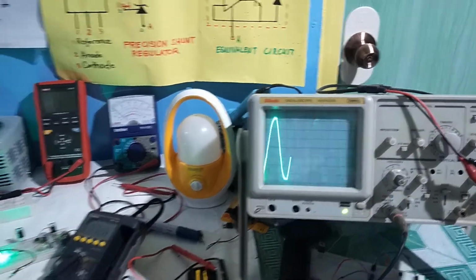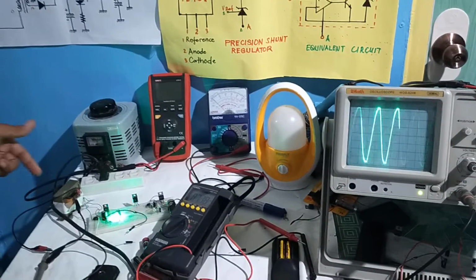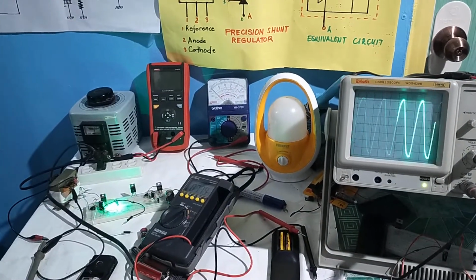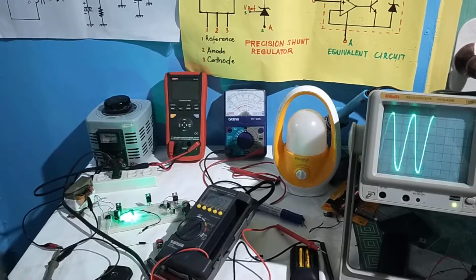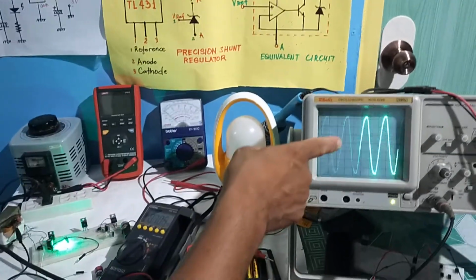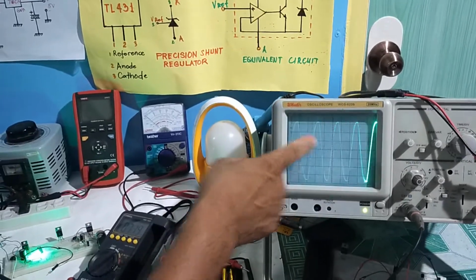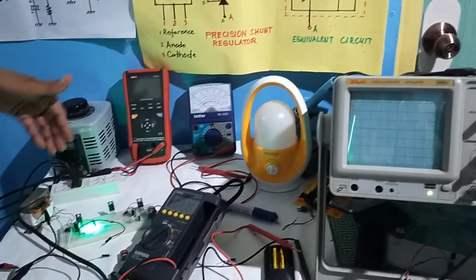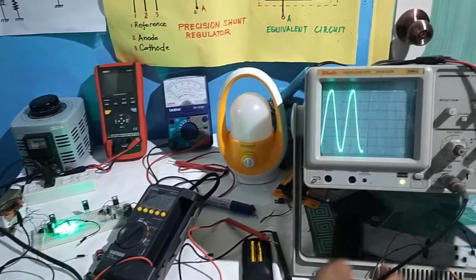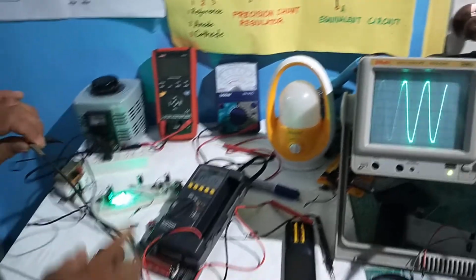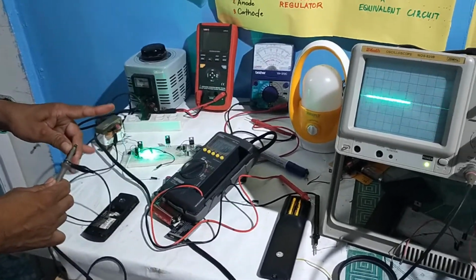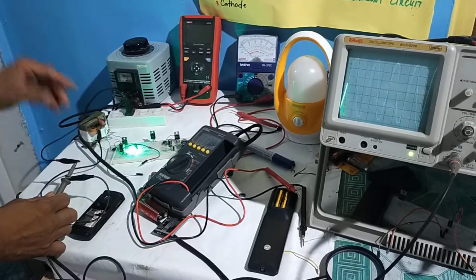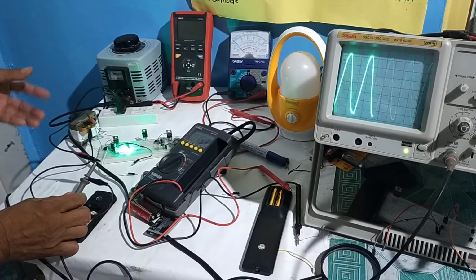It goes like that. Okay, let us measure. It is 12 volts. Remember that the voltage at the output of the secondary winding is 12.4 volts. This is now the waveform that is outputted by the secondary winding. The oscilloscope test probe we have here is connected to the secondary winding of the transformer. There are two terminals of this test probe.